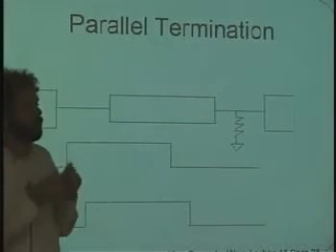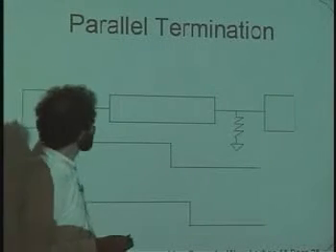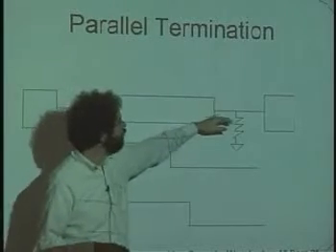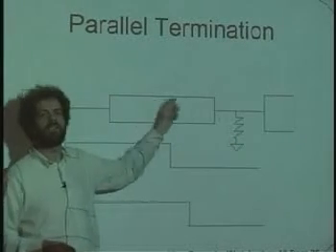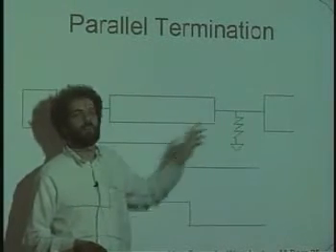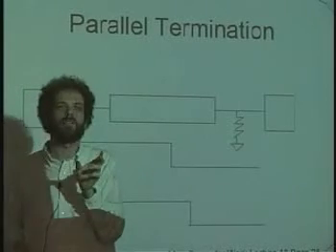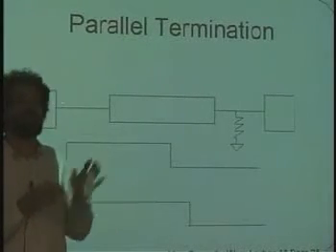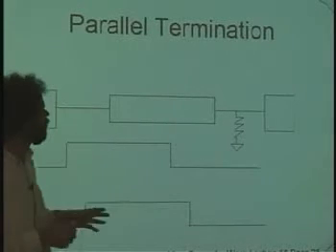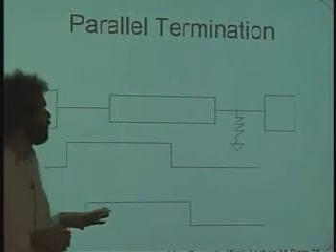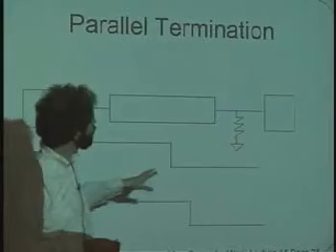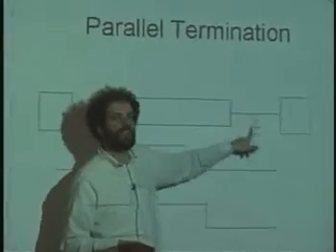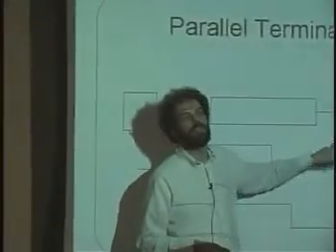And the reason is that when the computer sends a signal out on the bus towards the receiver, if it doesn't want the echo to come back to it, it needs to dissipate the energy. And so believe it or not, the terminators that you put there at the end, when data is being sent, they heat up just a little bit with the data that's being sent towards the other end of the line. And in computer design in general, particularly when you're dealing with high speed, you're going to discover that you're going to need to put terminators like this all of the time. And so modern computers have many more terminators than older ones have.